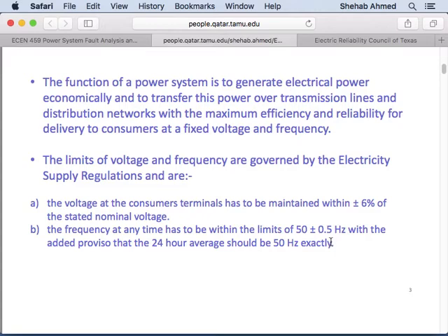So the generator requires you to have this force that will make it operate in steady state, right? So now what happens if you draw more power? If the load is drawing more power, that means there's higher force on the generator rotor.